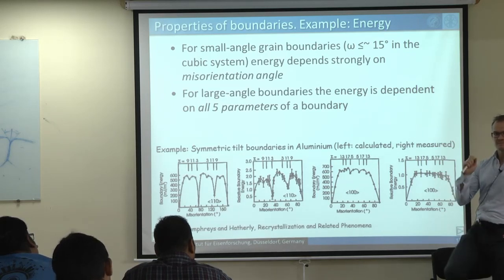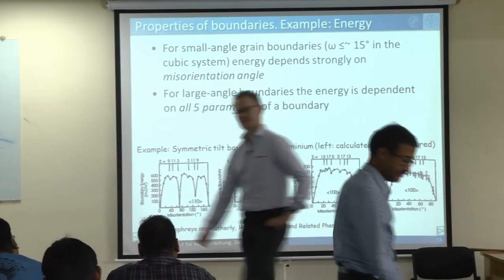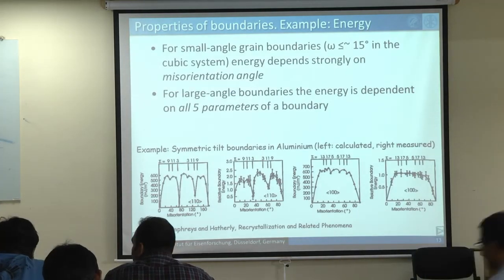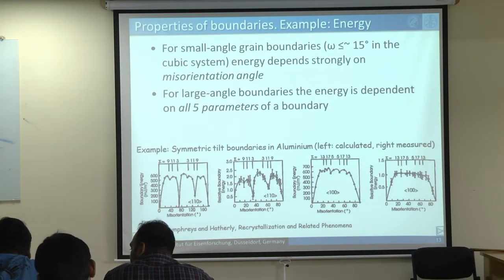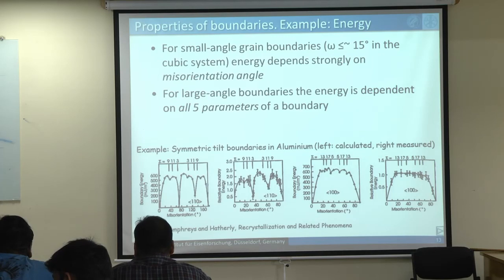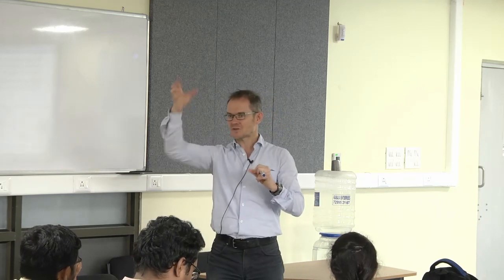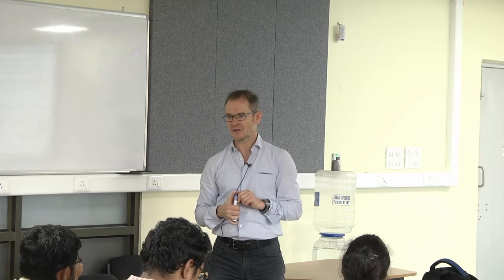And so these incoherent twins that form a part of the network, right? Only these incoherent twin boundaries that form a part of the random high angle network, like if you're trying to break down a network. Ah, you mean the grain boundary network from grain boundary engineering? Yeah, the coherent boundaries are important there, but the incoherent boundaries are like a network breaker. So they are actually really random boundaries. Yeah, they are. You cannot take them into account as a connector between two coherent ones. They really behave differently.